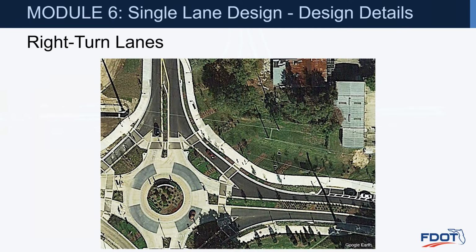Here's another example of a right turn bypass lane that really was added for no operational reasons. So we would recommend that these actually don't get constructed, because all you're doing is adding additional conflict points and potential confusion for the driver. But this design, due to the angle, has sort of a race to that spot, with vehicles circulating and exiting out of the roundabout, and then vehicles in this right turn lane. So that angle isn't necessarily the best.